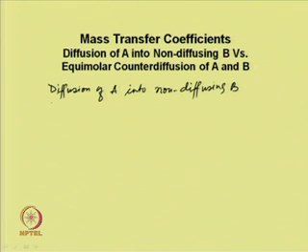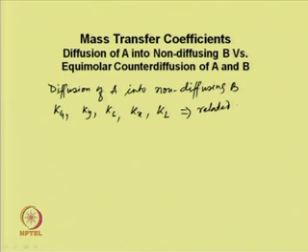the mass transfer coefficients, which are Kg, Ky, Kc, Kx and Kl, these are related with the log mean concentrations of the species.